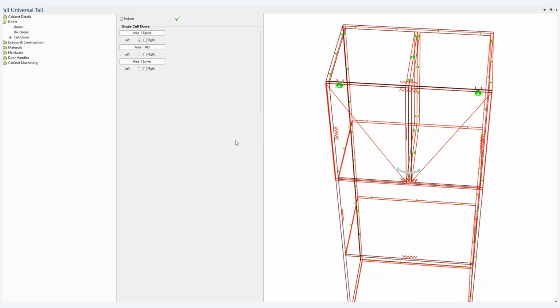At the moment, there is no allowance for variation in thickness when you're nesting the grid. It is a good idea, so we will suggest that. For the meantime, of course, you just have to measure the thickness of the material manually and alter the material thickness to ensure that the parts slot together correctly.